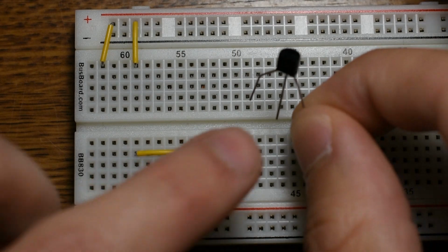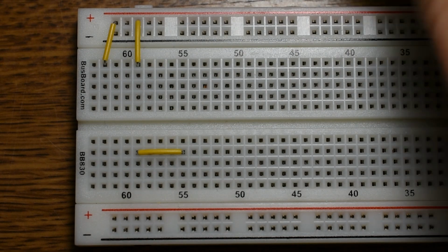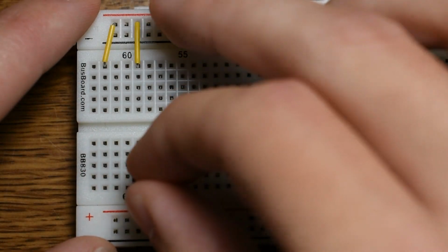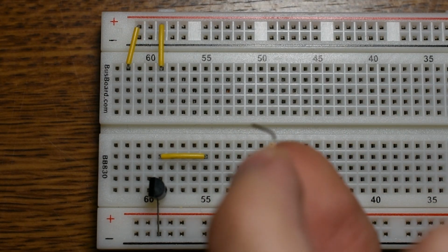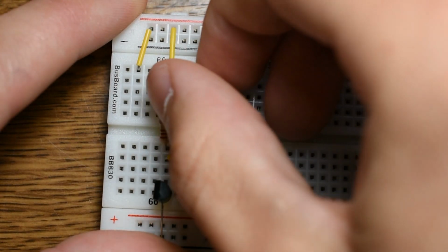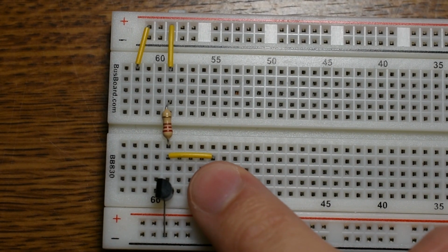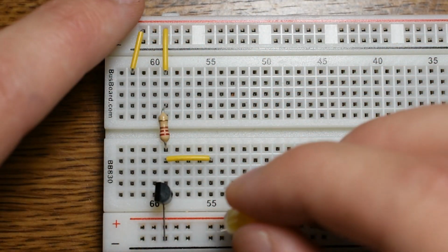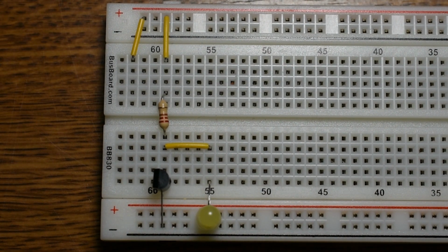So I'm going to connect the emitter to ground, which is this black rail at the bottom. And I actually have a modified transistor with the pins already bent how I want them. And then of course the collector gets connected to 5 volts through a 220 ohm resistor. And then we need the input and output circuitry. I already have a yellow wire here, which represents the output, and we can see the output with an LED. So when the LED is on, that means a 1 is being output, and when the LED is off, the output node is grounded, which is a 0.